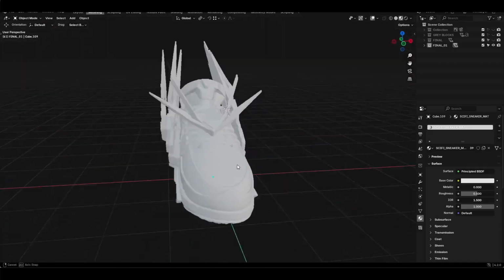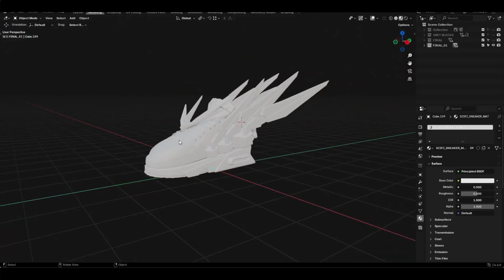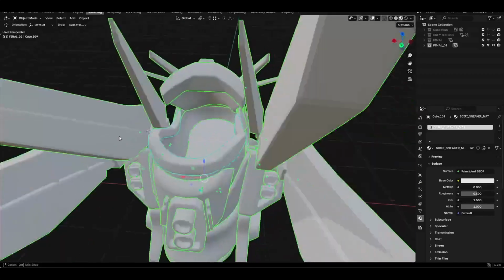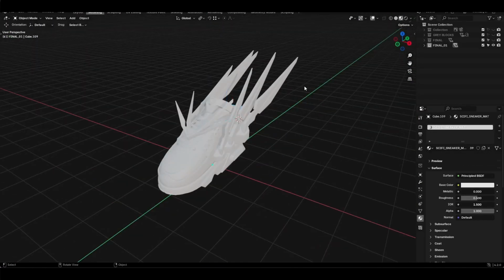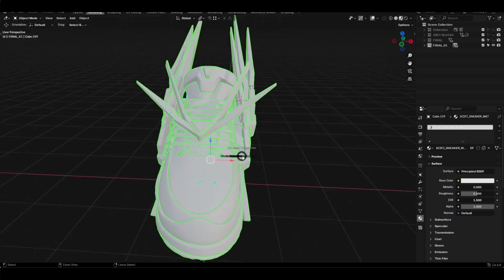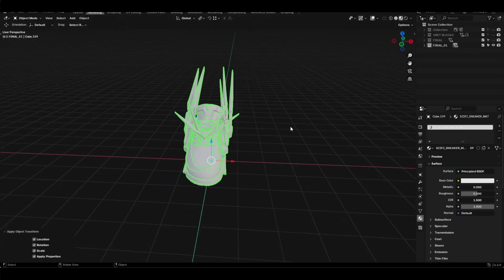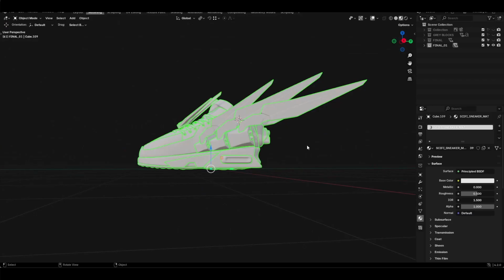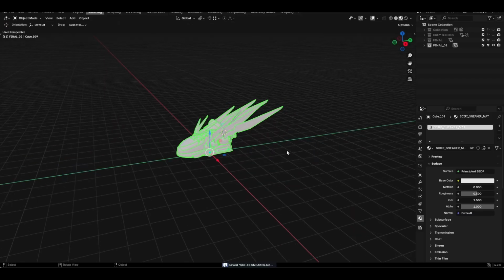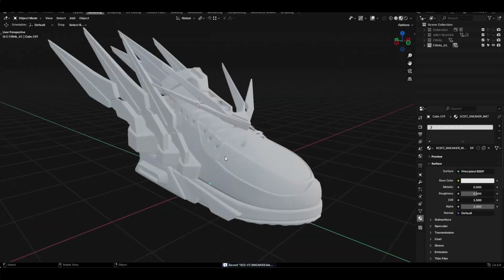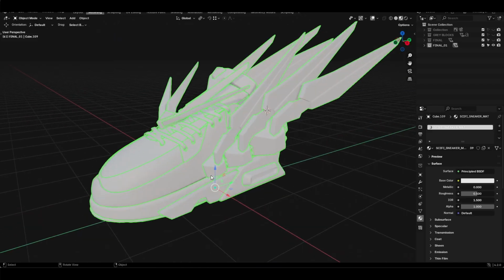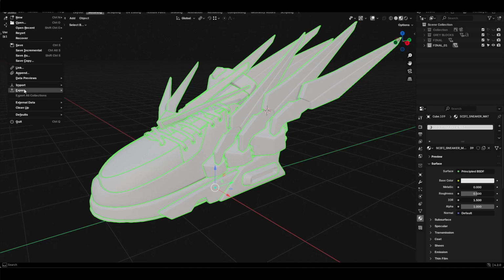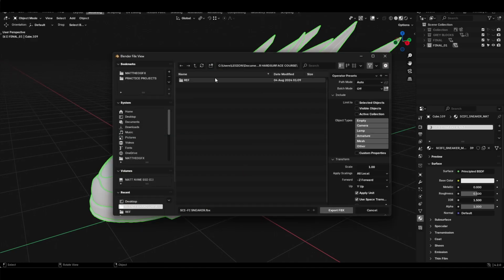Okay guys, so we have finished adding all the materials on our mesh. Now this model is ready to export. So let's select them all, Control A, let's apply everything, like deleting history. Control S. Let's save that. Next is we can now start exporting it. So let's select them, highlight, file, export, FBX. Then let's look for the folder that we want to save.